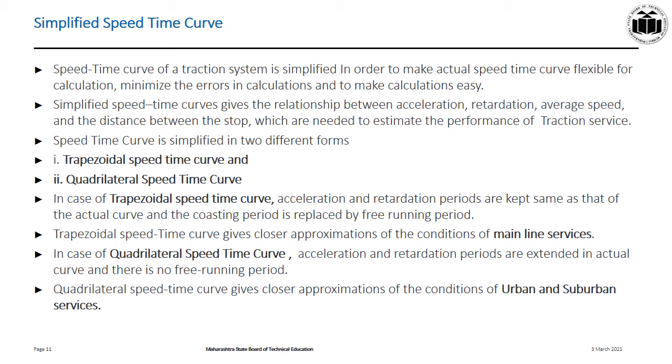Second, in case of quadrilateral speed time curve, acceleration and retardation periods are extended and there is no free running period in the quadrilateral speed time curve. The quadrilateral speed time curve gives closer approximations of the condition of urban and suburban services.